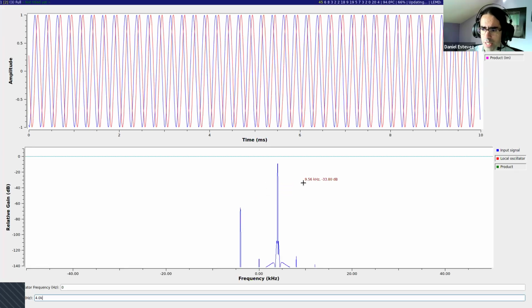So that is what a Hilbert filter does. It basically converts from real to complex by removing all the negative frequencies so that you only get the positive frequencies. That is the same thing as finding an equivalent signal like this, which for this very simple input signal is just lagging things by 90 degrees. But if we have a more complicated waveform in the input, then the complementary imaginary signal might look much more different from the input signal.